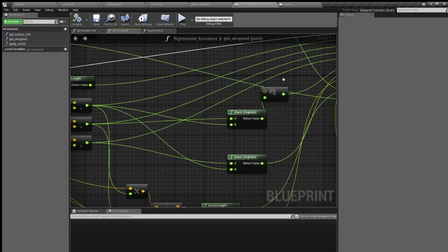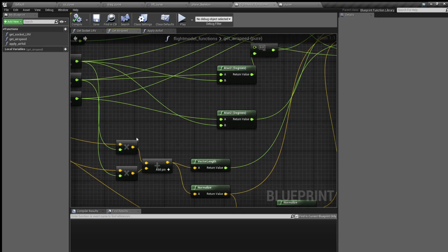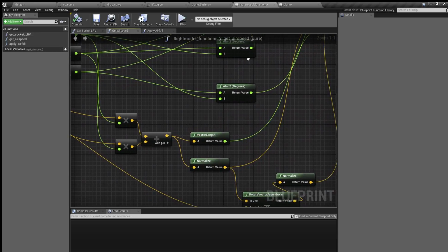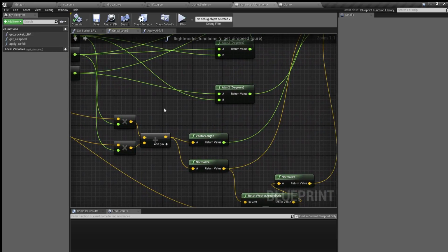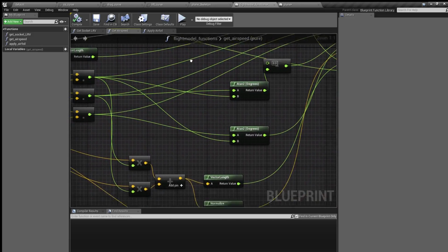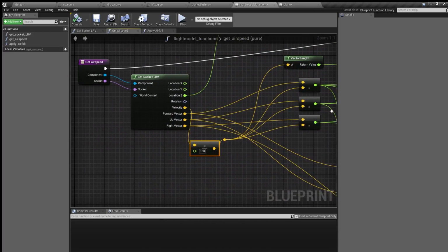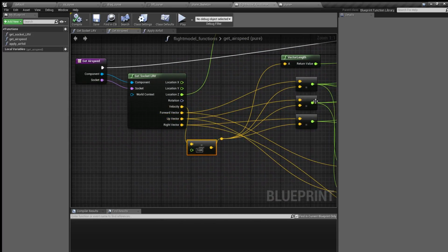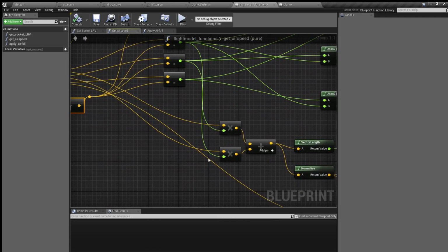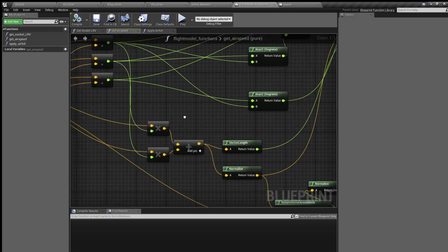It only uses airstream and alpha, which is the difference between the zero lift line of the airfoil and the actual direction of the airstream, which is calculated by simply multiplying the forward vector and up vector with respective velocities, and then just adding them up.